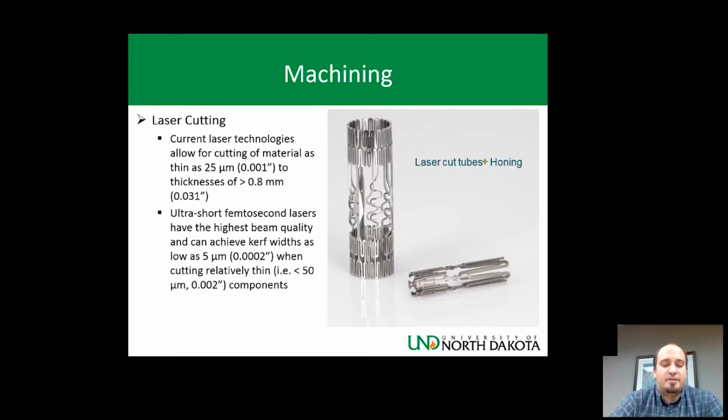SMAs can also be laser cut. For example, during the manufacture of a cardiovascular stent, the tube is rotated and moved longitudinally under the focused laser beam to create the desired cut geometry. Laser cutting has become one of the most commonly utilized machining technologies for the manufacture of SMA devices, mainly due to the extreme precision and low thermal input characteristics.